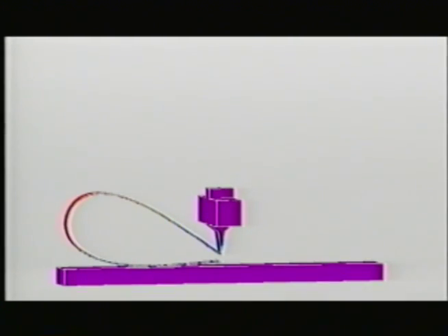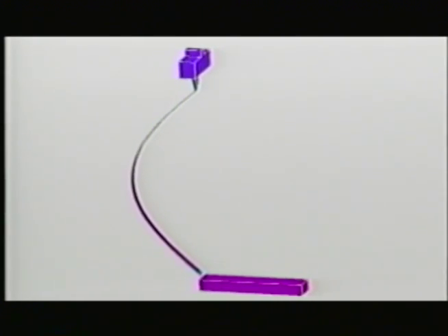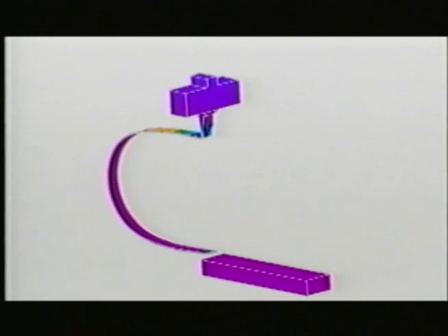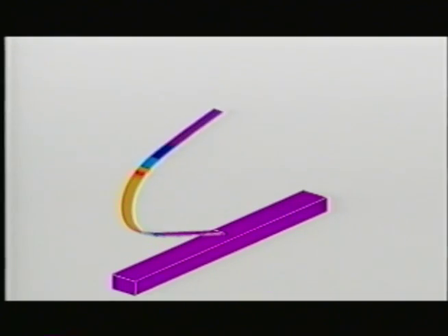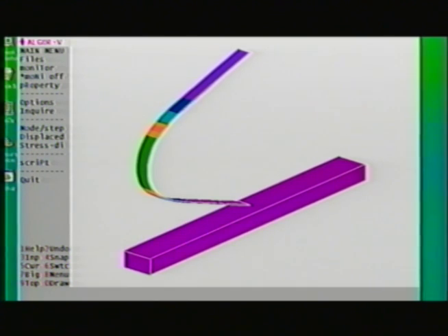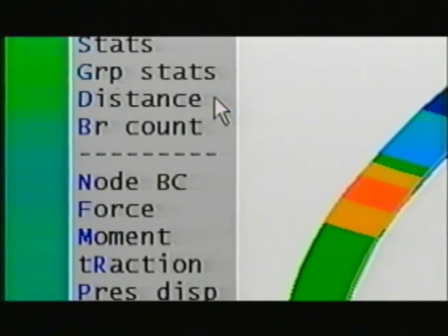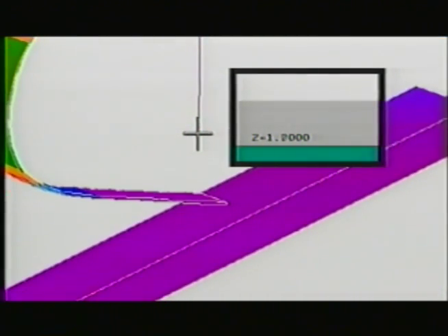Let's further examine the significance of the floor. Without it, we still get buckling, but it is nothing like the correct simulation. Finally, modeling the removal of all the weight, we obtain the permanently deformed shape. Measuring the distance between the 2 ends with SuperView, we obtain 16.5 inches separating them in the permanently deformed condition.